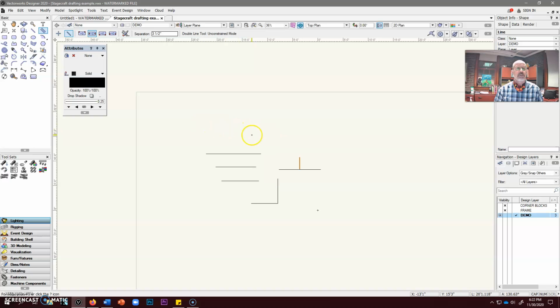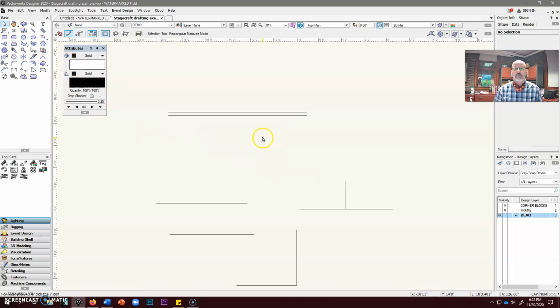And here's what happens when I use create lines. I'll draw 2 lines 3.5 inches apart from each other, and then I'll click X, which gets me back to my selection tool. Then I can select either one of those lines and do something with it. I can turn it, I can lengthen it, I can do whatever I like, right? Erase it.